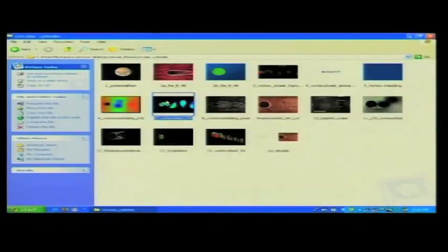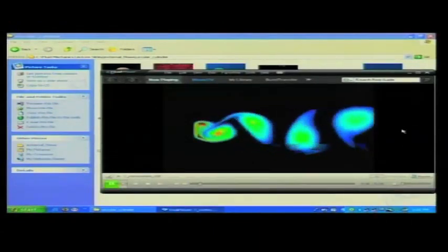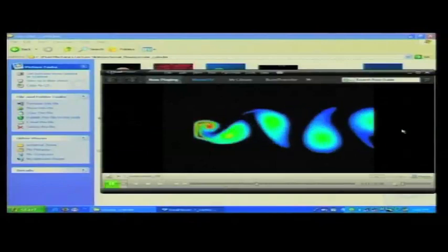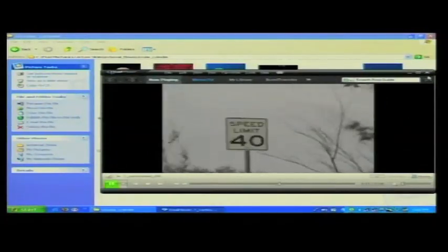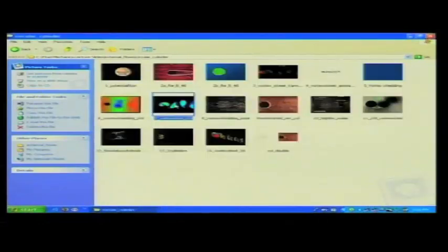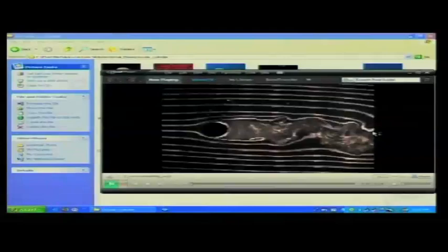Now, we will see some more examples of the vortex shedding. This is also an animated description. You can see that alternating vortices are shed in the fluid from the cylinder, and that occurs for quite a large range of Reynolds number, and it is important for many reasons, because we will see through one example what effect it has on the cylinder itself.